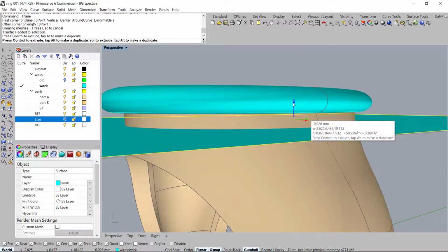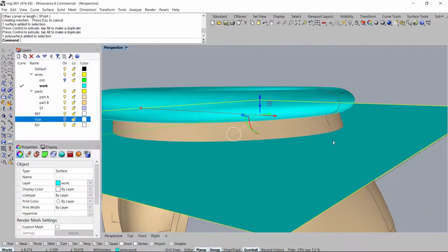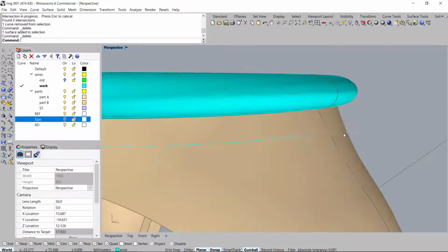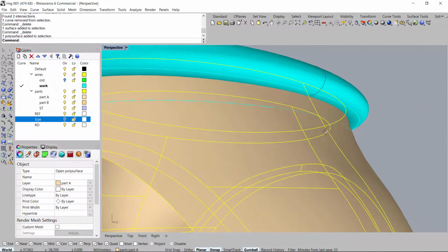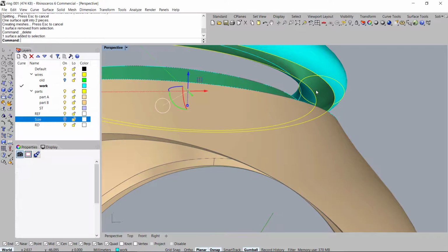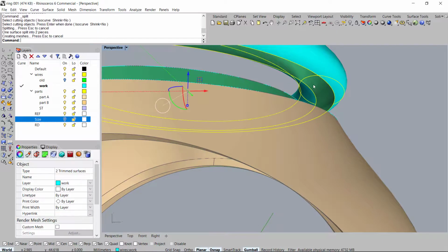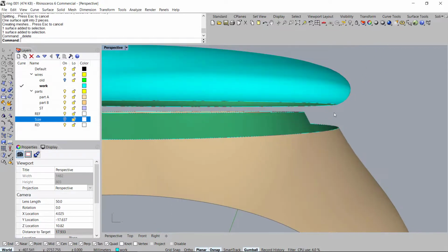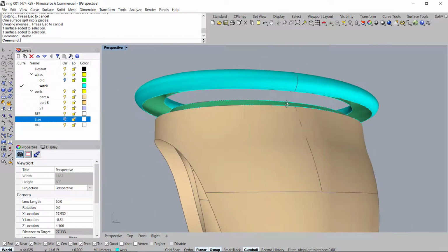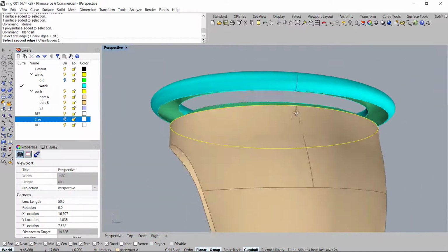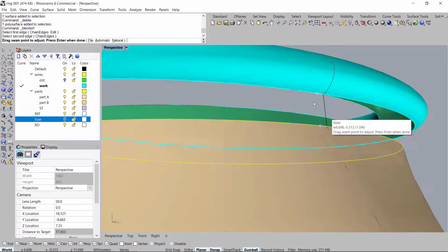Okay, so select the plane, the body. Again, you'll see it's pretty repetitive once you get the flow of what I'm doing. All right, so split it with that to expose that, and we'll split this to expose this. Go ahead and cut that inner part right there, so you can see we have that. Now we can actually start blending. Okay, so let's try blending this. Go with the blend tool, select this, then the upper.